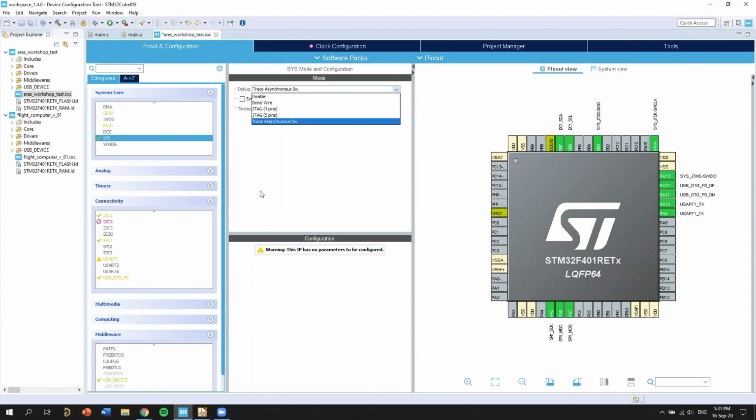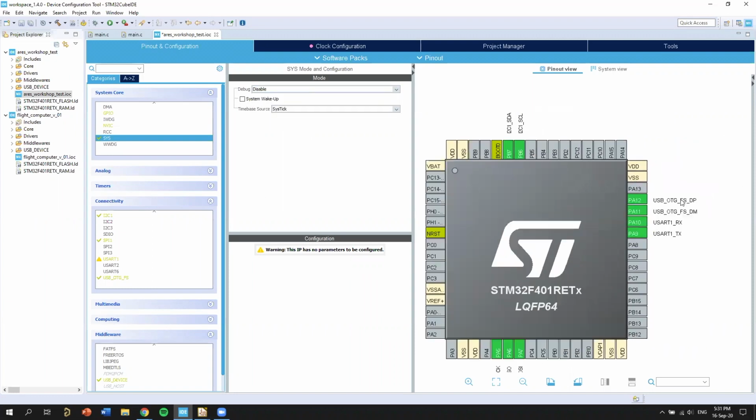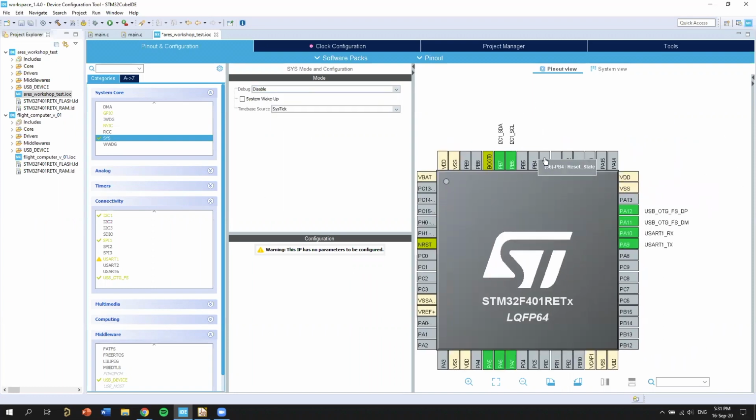You can see, if we turn this off, you can watch PA13, PA14, and then PB3. When we turn serial wire on, these two come on. This is how you program it: there's a clock line and a data line, for the very first time using the little dongle.